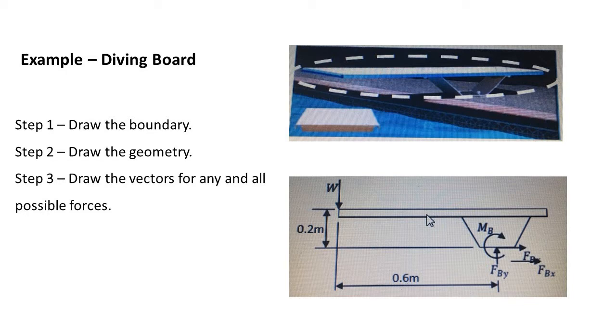Let's do another example. A diving board. Assume support for the base at 4 bolts. The diver stands in the middle of the board at the end, so there is a plane of symmetry through the board. The force on each pair, front and back, of the bolts will be the same.